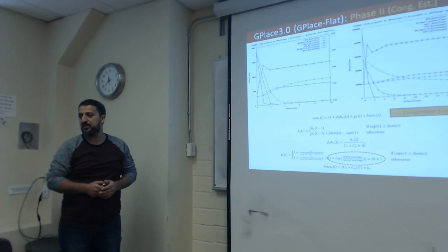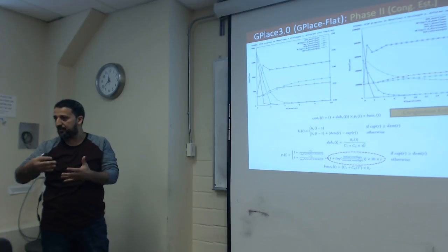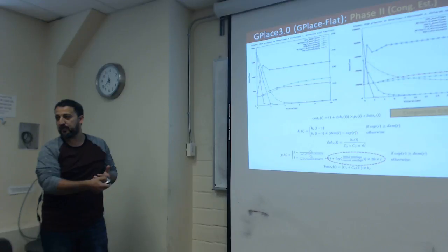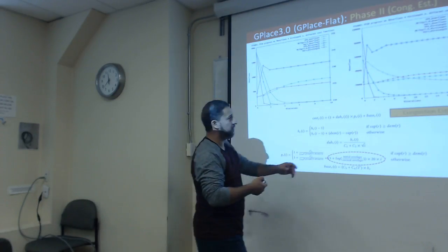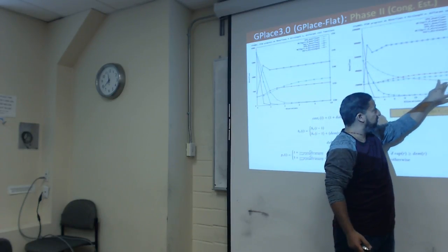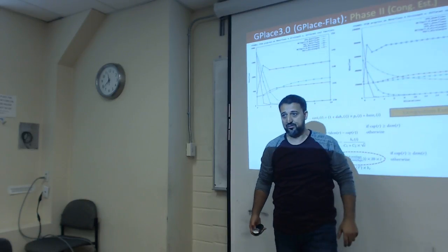Yes. But the idea here is that we are conservative with increasing the wire length, but also the job of the global router should be to get rid of the overflows. And here we found that for hard-to-route designs, the original cost function is not able to get rid of those overflows.